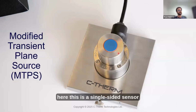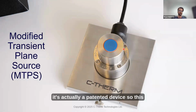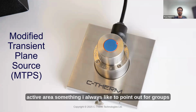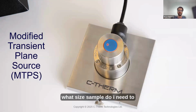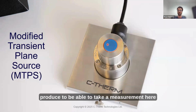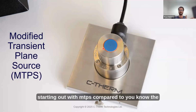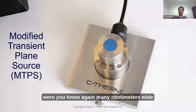The MTPS is a single-sided sensor design. It's actually a patented device, so this is available solely through C-Therm. The MTPS active area, something I always like to point out for groups, is about 18 millimeters in diameter. So when you're considering what size sample you need to produce to take a measurement, as long as we can cover the surface of that sensor, they're about the size of a quarter. Quite a stark contrast compared to the sizes typically needed for, let's say, a heat flow meter, which were many centimeters wide.